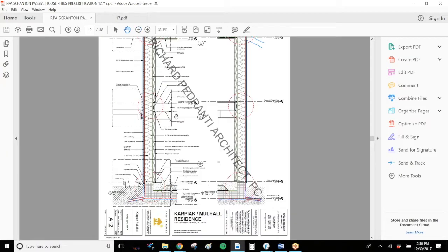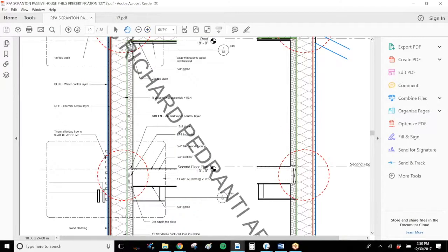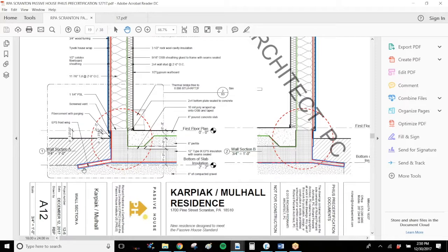If there's slab insulation that extends below the slab or out of the slab, such as this wing on the side, this can be entered as perimeter insulation. So here we may have a frost skirt or frost wing that's about 24 inches wide and maybe 2 inches thick. Based on this being about 12 inches, this appears to be about 2 inches.